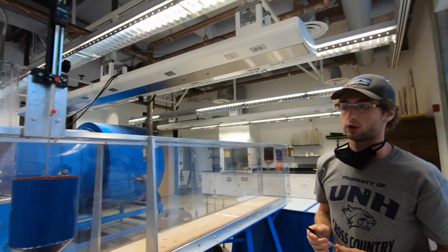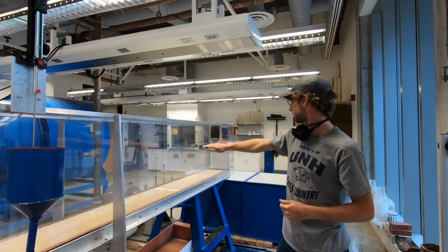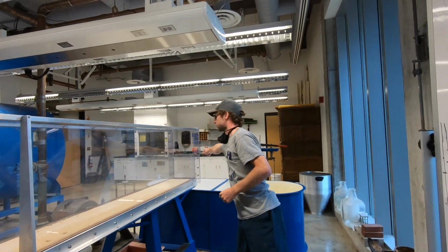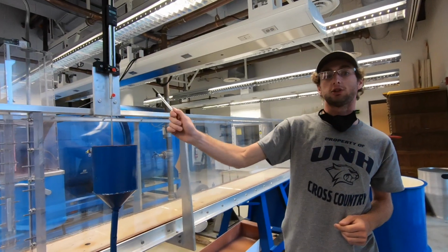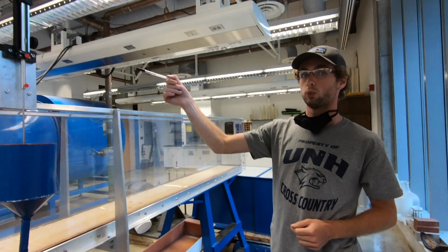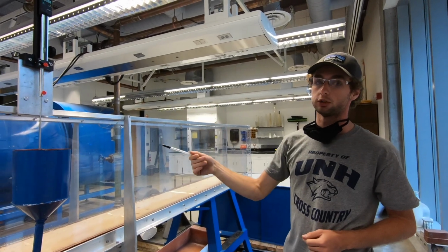At the end of all the trials, when we have the water sitting stationary in the flume level with the top of the weir, we'll get an additional hook gauge measurement, so that we'll know the height of the hook gauge when there's no flow and no height relative to the weir.